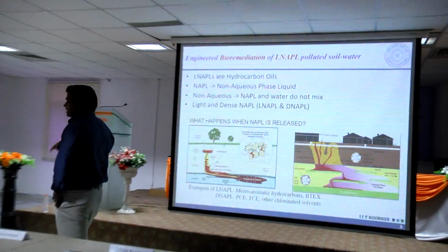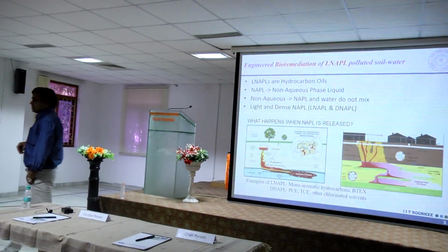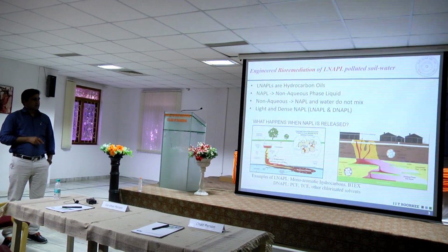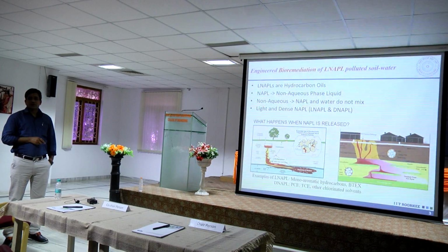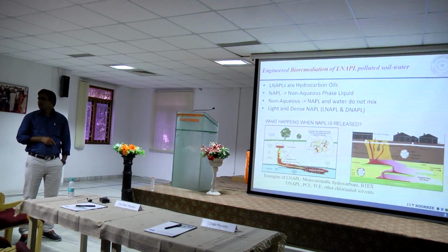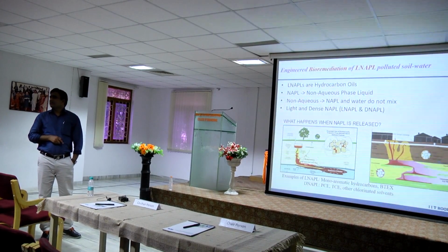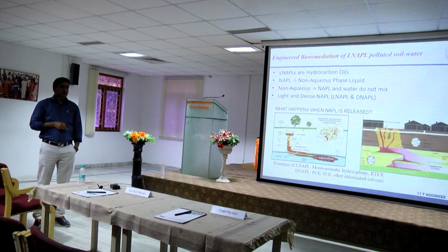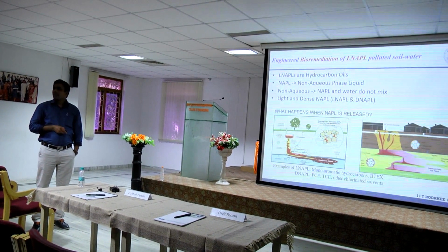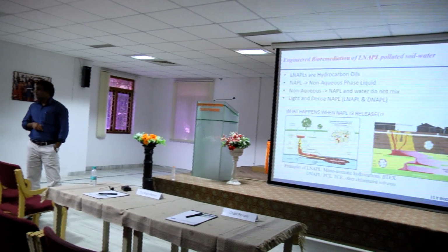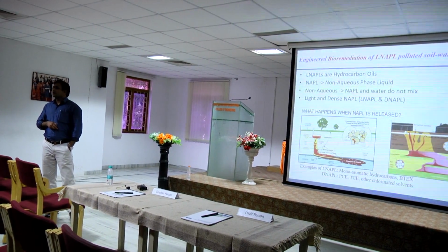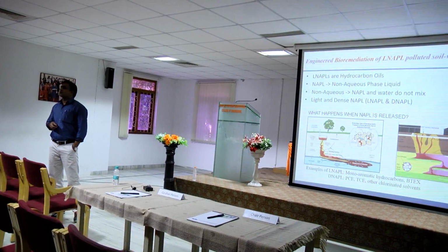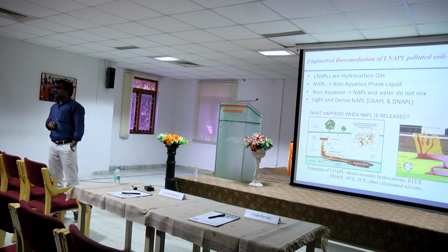Why? Because in the deep saturated zone, there is a limitation of oxygen. In this zone, we can see some transfer of oxygen from the ground surface through the soil to the water table, where these LNAPLs are, and they can be naturally attenuated. Naturally, they can be degraded. But in case of DNAPLs, they go into a deep strata where the oxygen is very limiting, and if the oxygen is limiting, things become anaerobic, and anaerobic degradation of these hydrocarbons is quite slow as compared to aerobic attenuation.